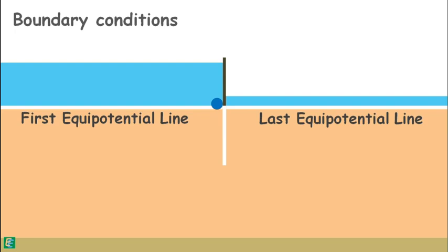Water molecules cannot cross this sheet. It flows from this point vertically downward, and after crossing the sheet pile, it will vertically ascend. This line is also tracing the flow path of the molecule, so this boundary, if we name it ABC, is a flow line.